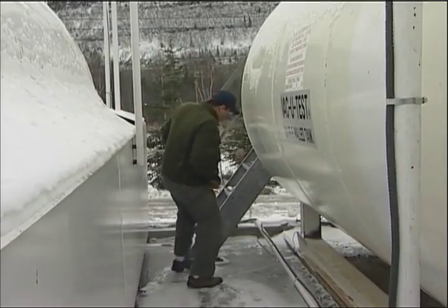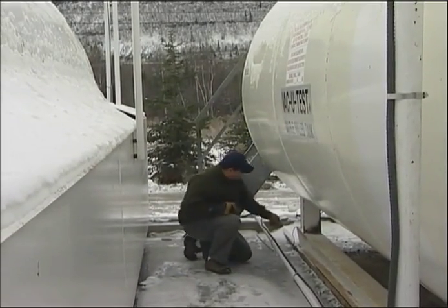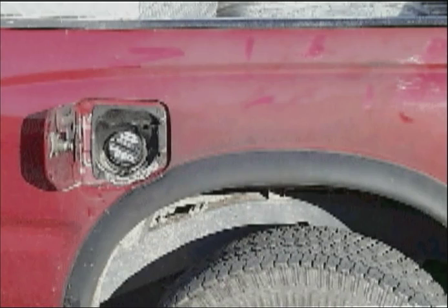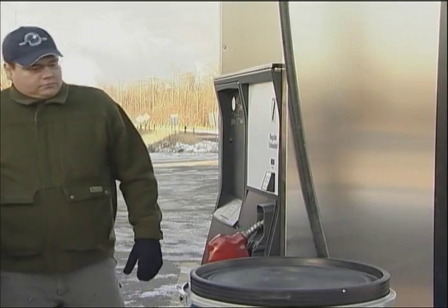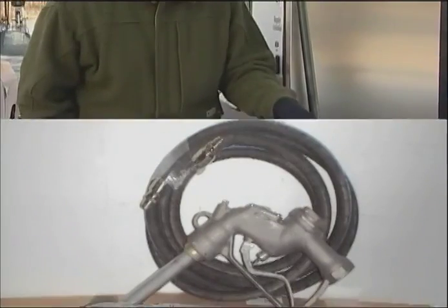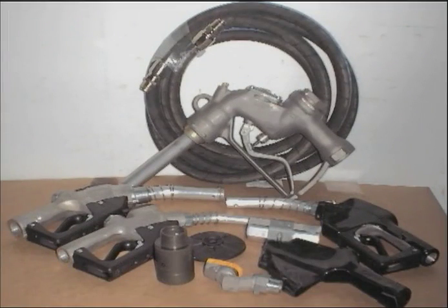Bulk, fuel tank, and fuel pump should always be grounded. Always make sure that you are using approved fuel hose for the dispensing of petroleum liquids. Hoses are manufactured with a ground wire molded right into the hose as a safety feature. A simple test can be performed to ensure your fuel hose and nozzle are grounded to your fuel pump. This test is known as a continuity test.